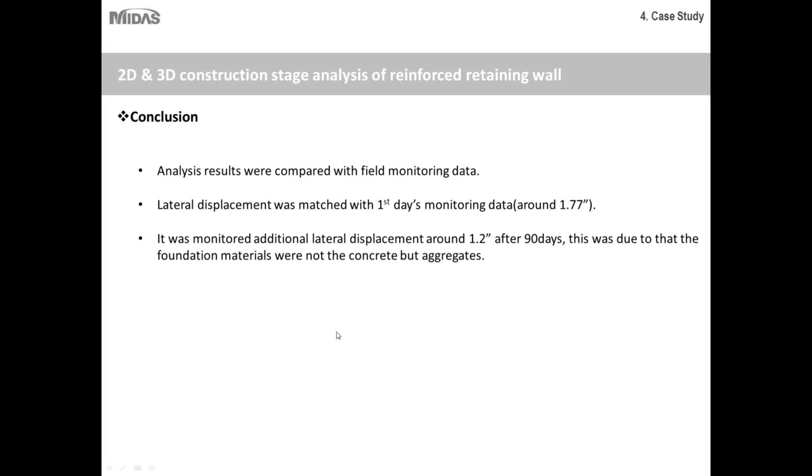Now it is quite obvious, it's not very hard to understand, that if your foundation is not concrete and not monolithic with your wall member, then it is highly likely to have an additional lateral displacement as the soil stabilizes, or the stresses are relieved, or the soil is consolidated, and that's why we were having higher member forces in the lower reinforcements. So they were able to create the model and monitor the long-term effects of this analysis and how the wall would deform and match the results.